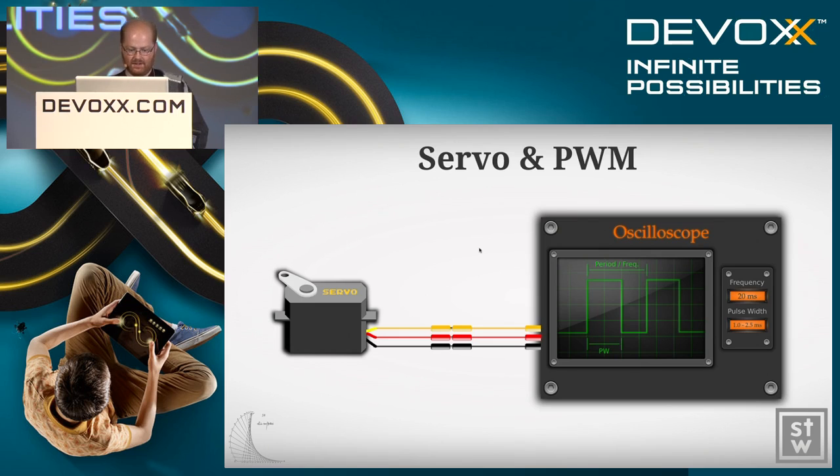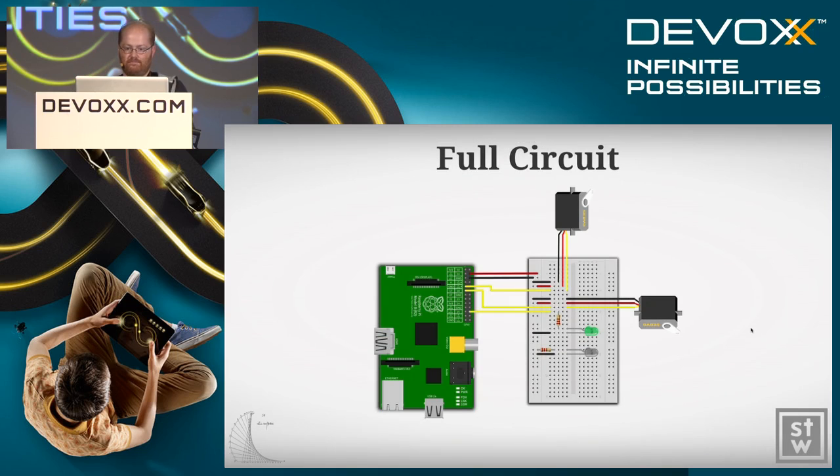So I integrated a project called Pi Blaster and Servo Blaster, which are just small libraries, and they are part now of the Java API here, so you don't have to worry about compiling C code or stuff. It's already done. And then you can create this pulse width and frequency. So the frequency is about 20 milliseconds, and the pulse width is 1 to 2.5 milliseconds usually. And then you can control the movement of the servo.